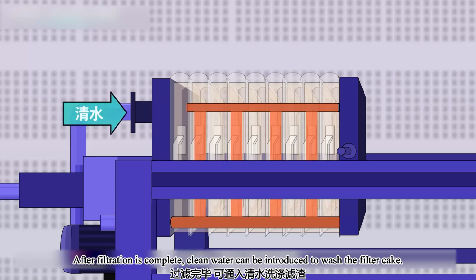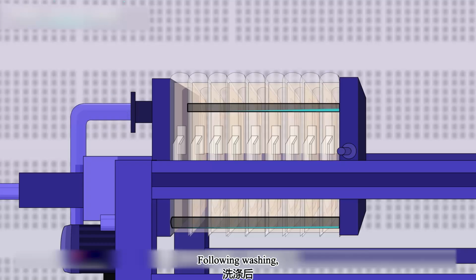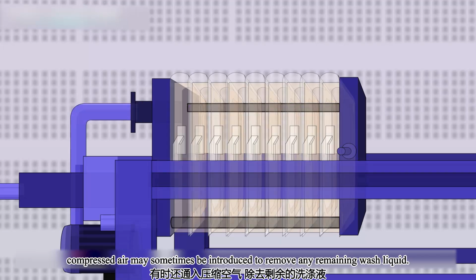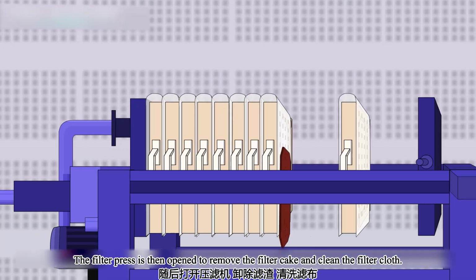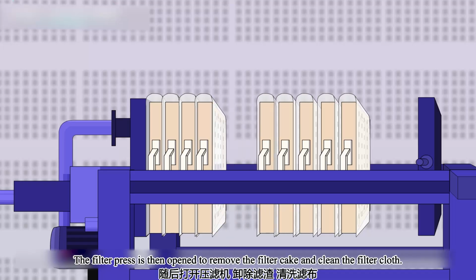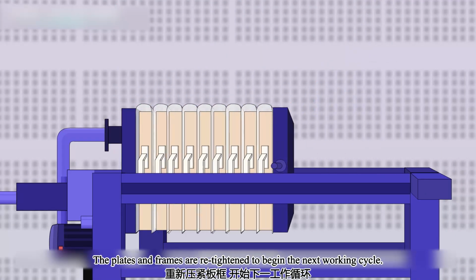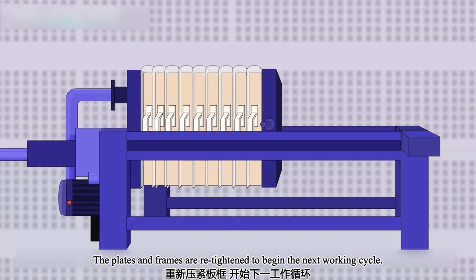After filtration is complete, clean water can be introduced to wash the filter cake. Following washing, compressed air may sometimes be introduced to remove any remaining wash liquid. The filter press is then opened to remove the filter cake and clean the filter cloth. The plates and frames are re-tightened to begin the next working cycle.